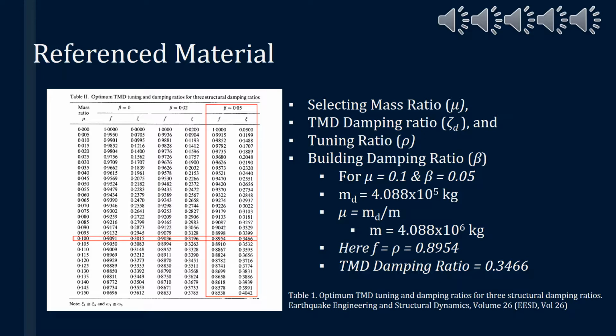From our research, we found that the One Rincon Tower has 2 tanks of liquid damper. Each contains 54,000 gallons of liquid water. From here, we converted gallons of water to mass in kilograms, and obtained a mass of 4.088 times 10 to the 5th kilograms for the damper.